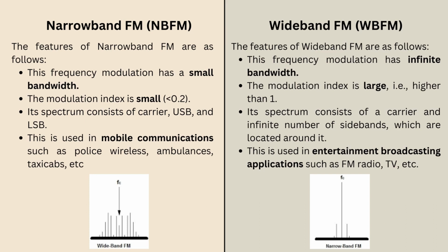For wideband FM, the frequency modulation has infinite bandwidth, the modulation index is large, and its frequency spectrum consists of a carrier and an infinite number of sidebands, which are allocated around it. This is used in entertainment broadcasting applications such as FM radio, TV, and so on.